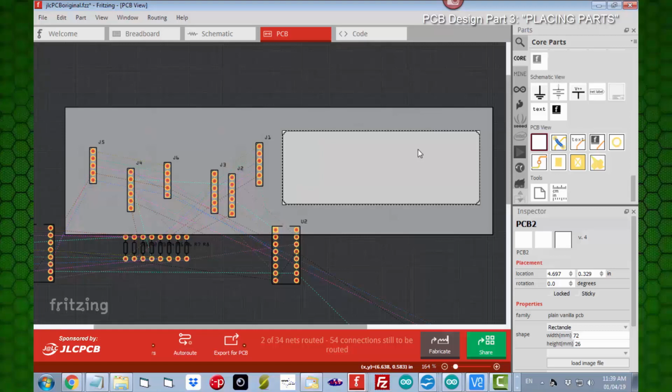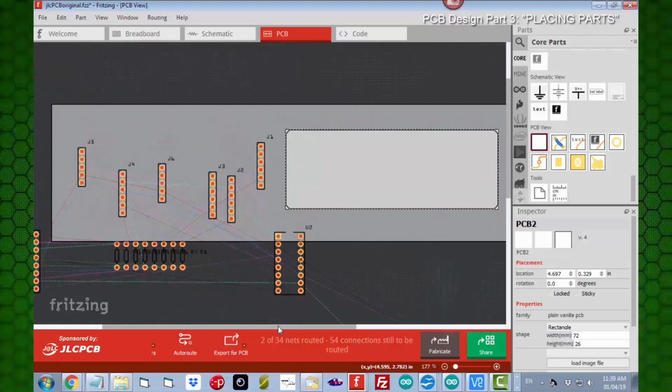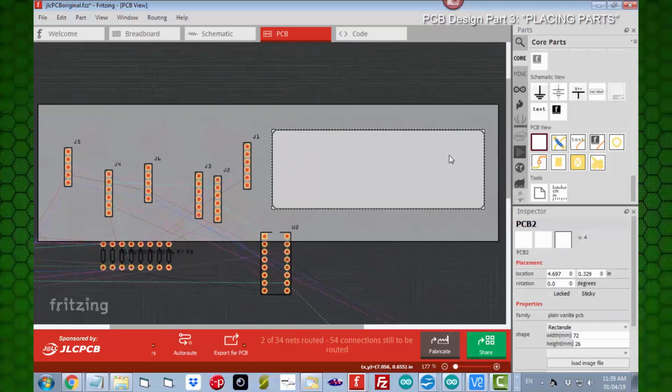Now, I'm going to show you a technique that I think will be helpful, a clever way of positioning this new panel, the dummy panel, in the right place. There will be 2 of these panels, and I want them to be centered on the real PCB. So I'm going to take this PCB, which I've highlighted here, and I'm going to go down here and cut this in half.